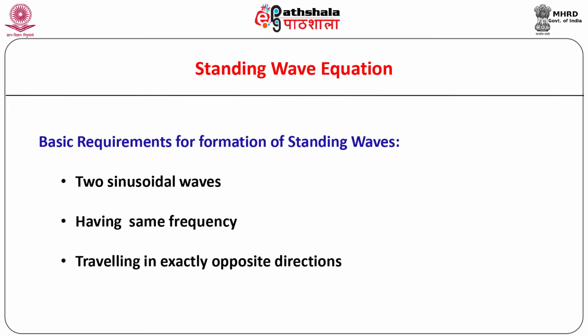Along the transmission line, there are two sinusoidal waves, namely incident and reflected, having different amplitudes travelling in exactly opposite directions. From our undergraduate study of physics, we know that such an interaction of two sinusoidal waves of different amplitudes travelling in opposite directions along the same line will give rise to a new type of resultant wave known as stationary wave or standing wave. Accordingly, we will have the presence of standing waves along the transmission line.